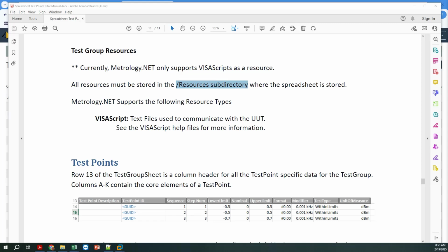So instead of telling the 3458 to go to the 10 meg range, what we've added into the 3458 drivers is the output current at each one of those ranges. And if it sees a current specification, then it auto ranges up until it meets that current specification. So does that answer your question, Scott?